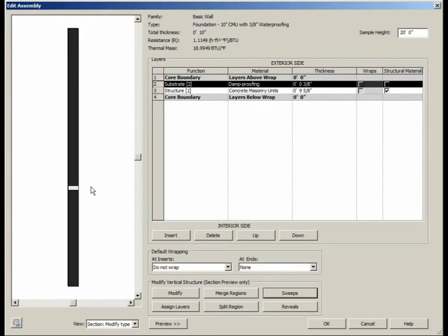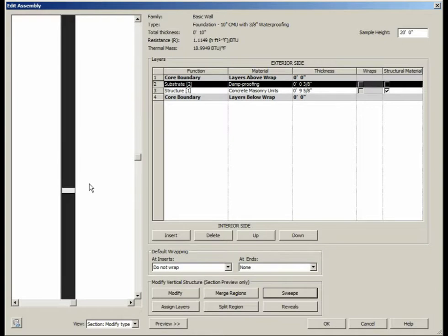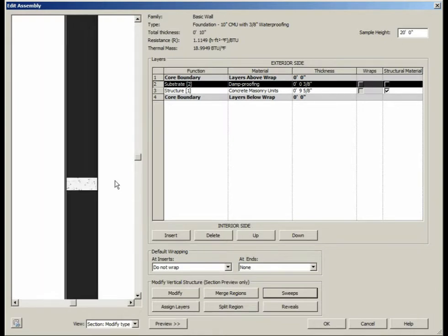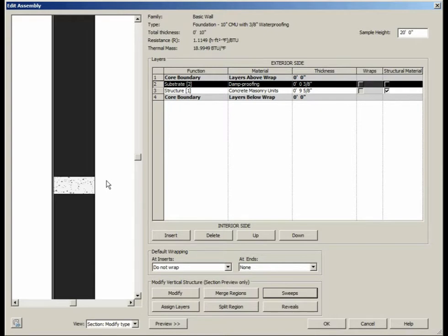In order to zoom in, select inside of the window where the wall and the cap block are, and use the scroll button on your mouse. You should be able to see that the edge of the cap block is on the inside edge of the wall.